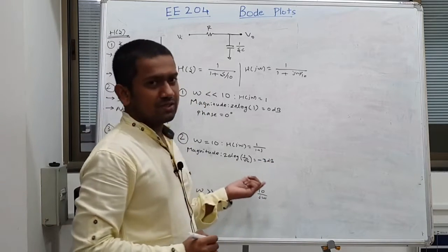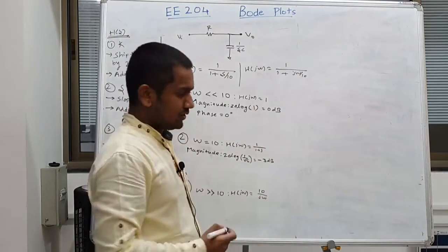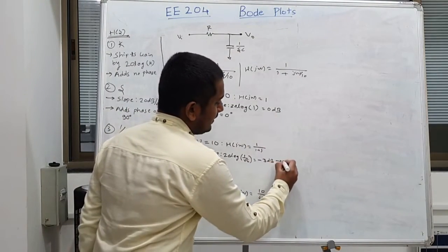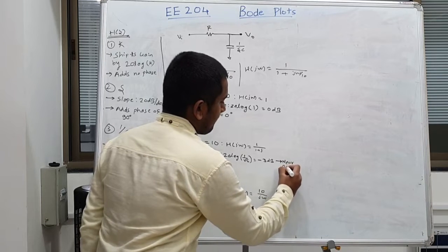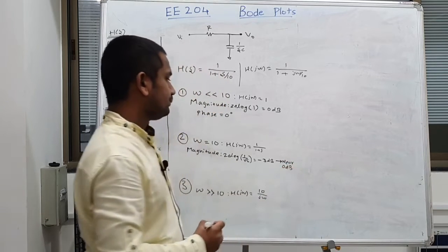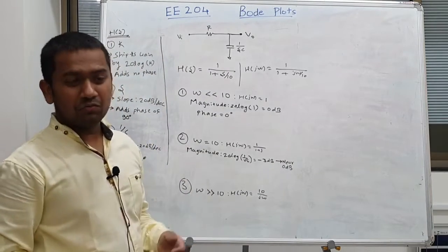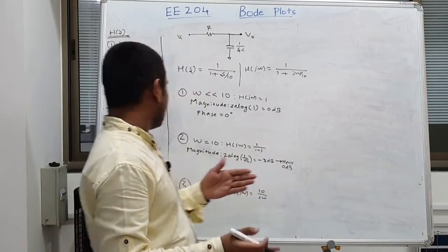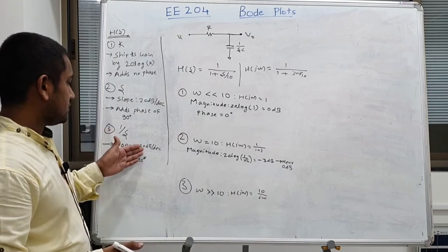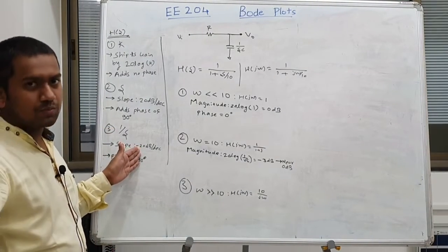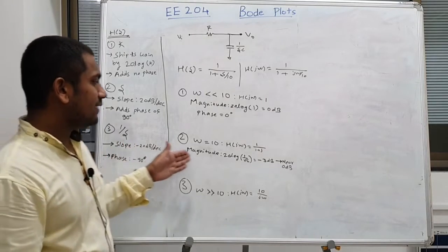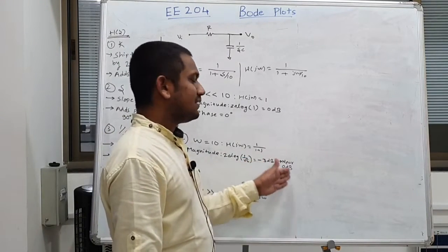Our first approximation for drawing asymptotes is that this is near 0 dB. Compared to that, if we look at one decade, the pole drops again by 20 dB. In 2 decades it drops by 40 dB. So comparatively minus 3 dB is near 0 dB.